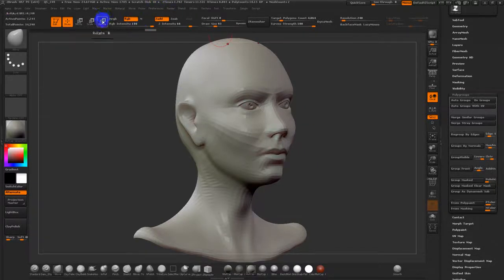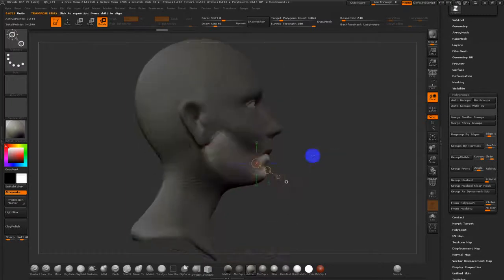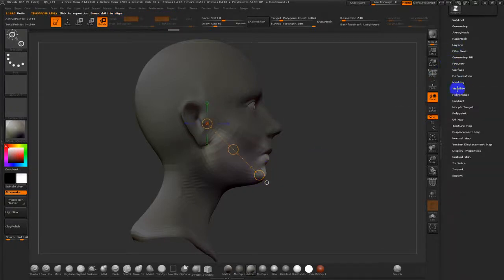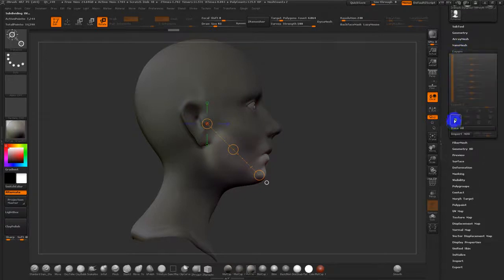So you can go to, let's say, the rotate tool, control click on the jaw, and then I'll control tap once, maybe twice. And now, if I go into rotate, so let me go back and set this up, here, I'll turn on my subdivisions. I'll go back to layers. So now I can go about creating my blend shapes, right, with a mouth cavity this time.